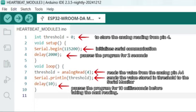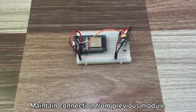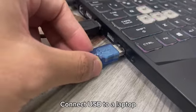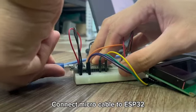Module 1.2, read the analog input, potentiometer, and LCD display. We need to maintain the connection from previous module. Add LCD to the breadboard. This is the connection diagram. Connect the LCD to the breadboard. Then we connect USB to the laptop and connect micro cable to ESP32.